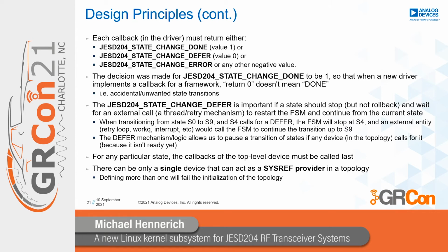The defer mechanism logic allows us to pause a transition of states if any device in the topology calls for it because it isn't ready yet. For any particular state, the callbacks of the top level device must be called last. There can only be a single device that can act as a SysRef provider.